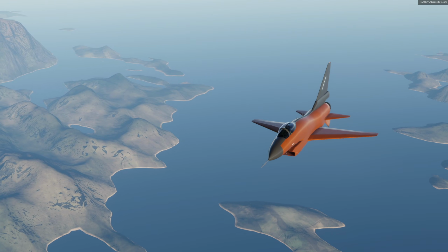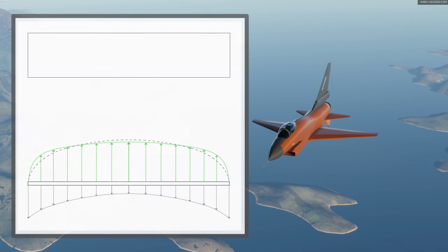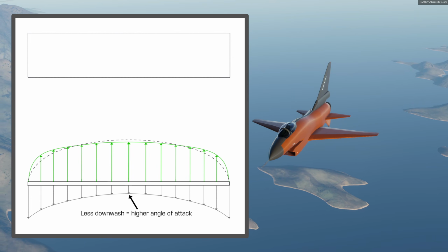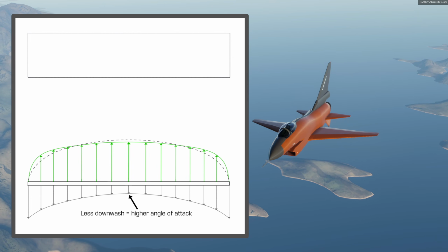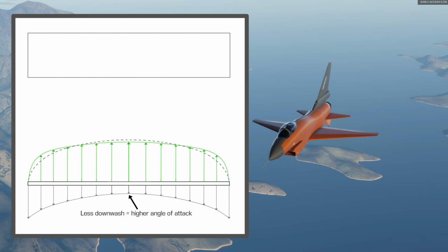Now is a good time to discuss stall progression on certain wing shapes. Starting with a rectangular wing and recalling its downwash distribution, we can see that the inboard sections will experience the highest angles of attack and will stall first, while the outboard sections stall later.